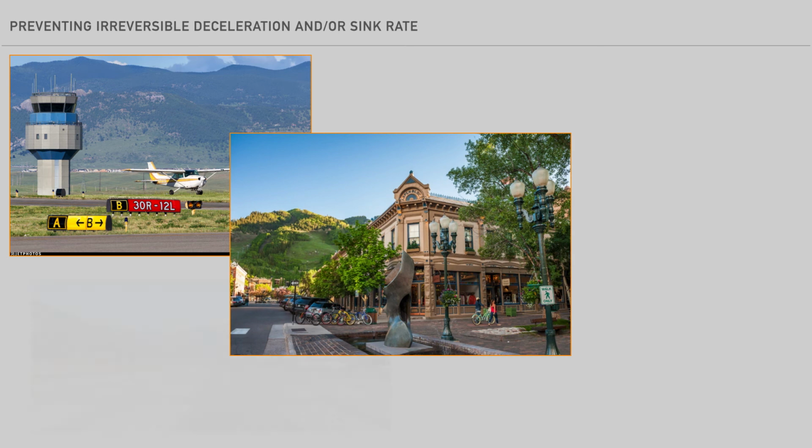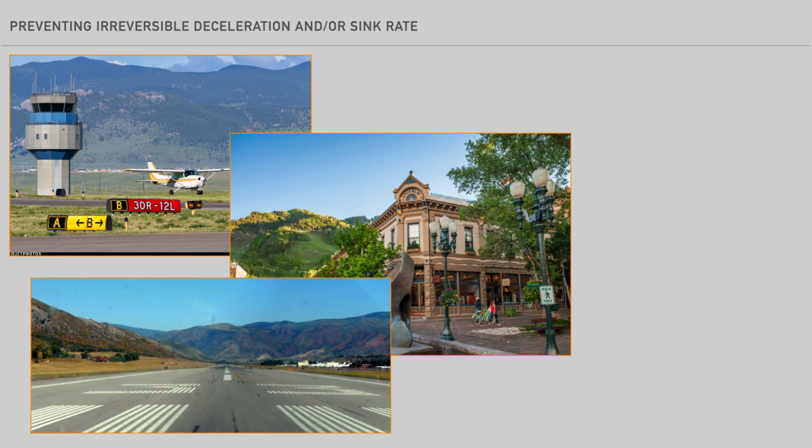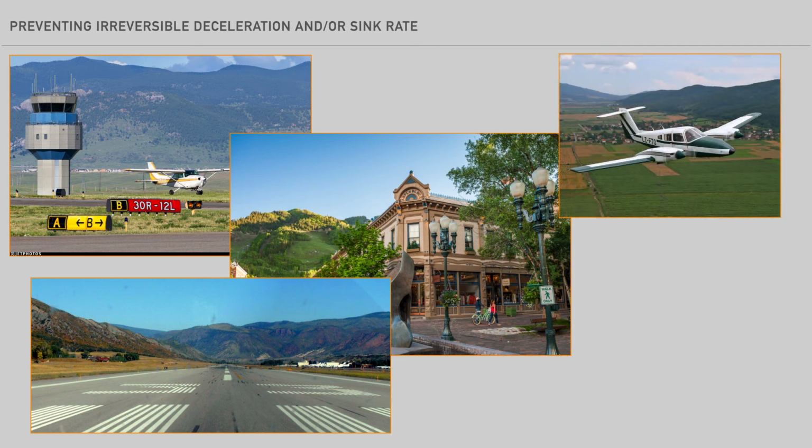The pilot departs Aspen off runway 33. At full throttle, the airplane takes longer to accelerate, but rotates at the normal speed. The pilot pitches for a normal climb attitude, retracts the gear, and initiates a climb. Soon the pilot notices the airplane isn't performing as expected. They check to confirm the gear is up and adjust the mixture to try and get a little more power.